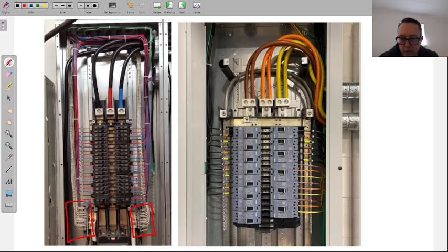They are all either using 2 phases or 3 phases. You will notice not a single neutral other than the main one that comes in. Lights and single phase circuits could have been pulled out of this panel, but you'll notice this panel has all multi-wire branch circuits. All multi-wire branch. Not a single neutral in use. So there are the 2 differences in the ways circuits get wired up. A lot more use for neutral loads in the 120, 208, 240 volts.